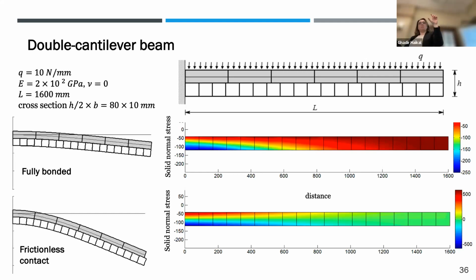So they behave as one beam. And as you can see, the stress distribution is corresponding to that. I have a bending stress distribution, tension at the top, compression at the bottom. The second solution is where I am debonding the two beams, and therefore they each bend independently. And you can also see that in the solution on the right.